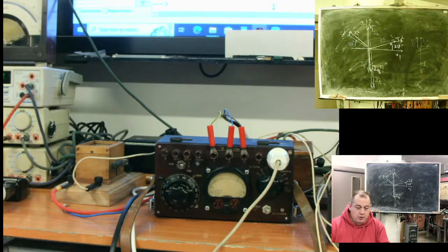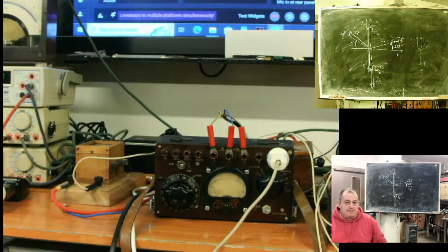Through motor flows 1.69 amps of negative sequence and 2.3 goes to net. So motor is 70% of the network. Quite significant thing. Yeah? Okay.